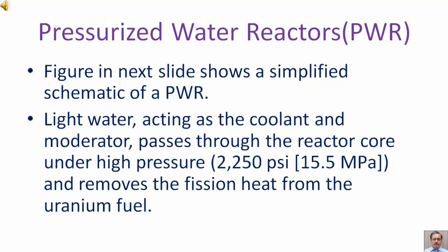Pressurized water reactors, that is PWR. The figure in the next slide shows a simplified schematic of a PWR. Light water acting as the coolant and moderator passes through the reactor core under high pressure, that is 2250 psi, and removes the fission heat from the uranium fuel.